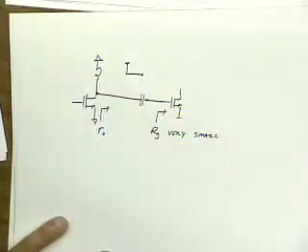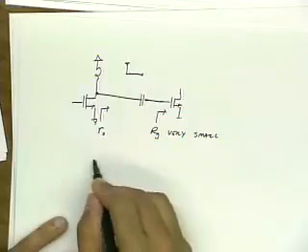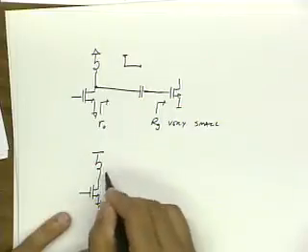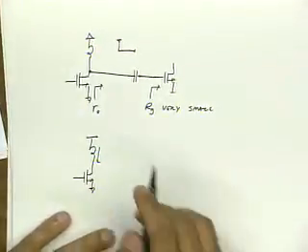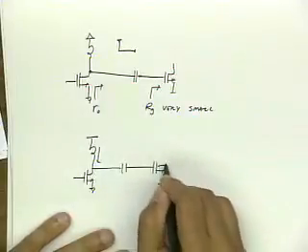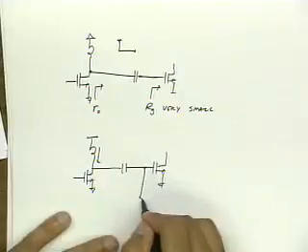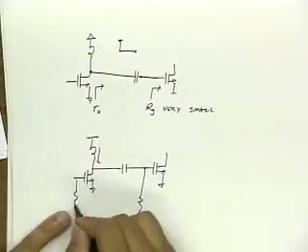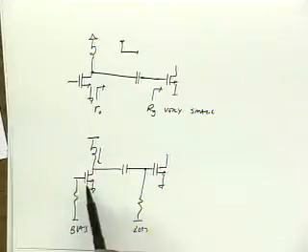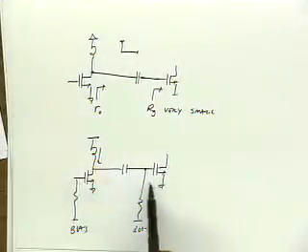Well, this is actually very convenient because, first of all, I can now put this inductor to the power supply, and it provides a DC current for this stage. And this capacitor automatically provides AC coupling, so I can now bias this stage separately from this stage. So this is a very nice, convenient topology. Well, the downside, though, is that what if we wanted to low-pass filter the output of this guy before it drives the second stage? This is doing the opposite.